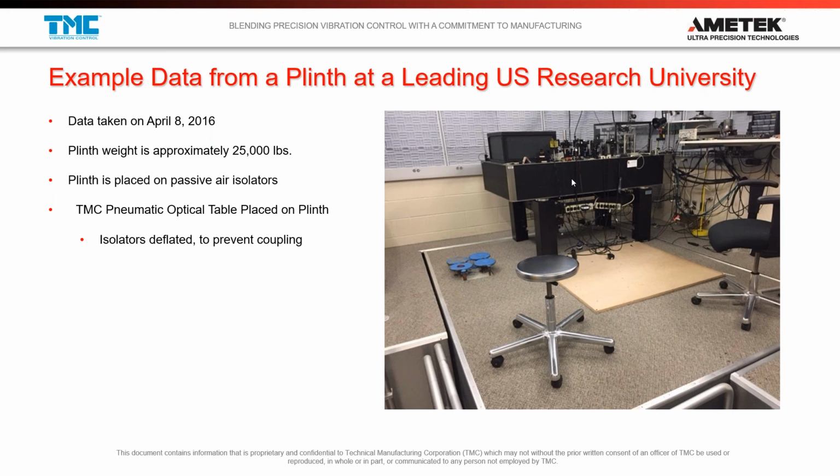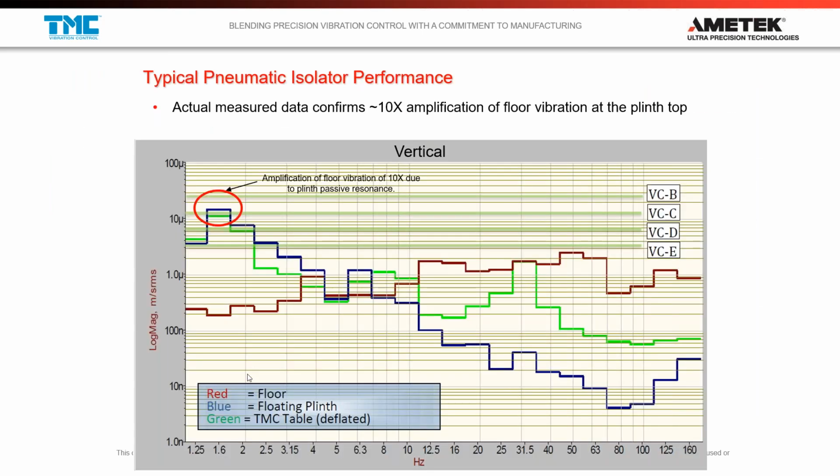No, they had a good separation of mass, but the resonant frequencies that were low frequency were summing, to a point where the 2 hertz resonance of the plinth plus the resonance of this one was so bad they had to deflate these isolators. So it became kind of a useless second stage of the system.